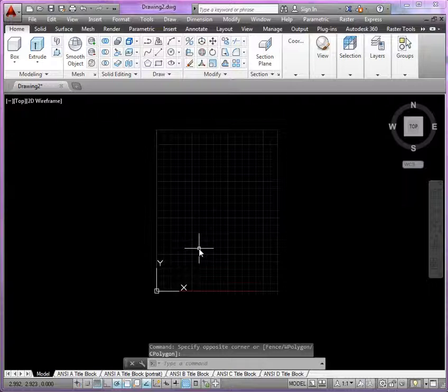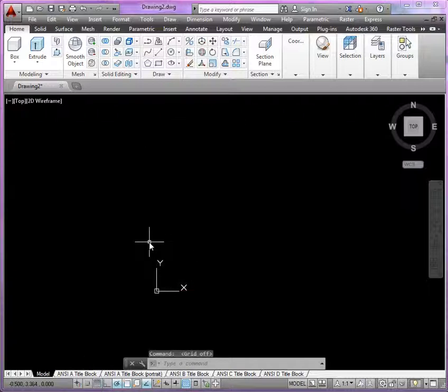Now since we're going to be using layouts for our presentation, we really don't have a need for the grid here, but just keep in mind the F key shortcuts to turn on and off most of your drafting settings, as this is going to help your drafting. Okay, either to locate or visually see the UCSs as they change, or even to control the O-snap to turn that on and off. The other thing is too that when you're ready to annotate, just pay attention to your annotation scale here.